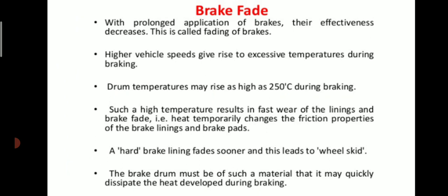What is brake fade? When with a prolonged application of the brakes their effectiveness decreases, this is called fading of the brakes. Higher vehicle speeds give rise to excess temperature during braking. Drum temperature may rise up to 250 degrees centigrade. See the temperature range, 250 degrees centigrade, during the braking. Such a high temperature results in fast wear of the linings and brake fade.